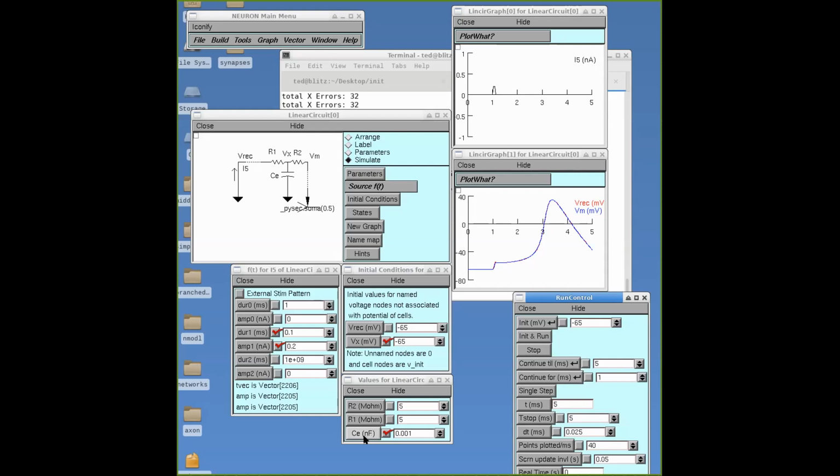Now, for those of us who are electrical engineers, we realize that 1/1000th of a nanofarad is simply a picofarad, and a picofarad is actually not that small for certain purposes. And it's no surprise that something on the order of 10 or 100 picofarads could load down a signal source as delicate and small as a model cell with its Hodgkin-Huxley currents.